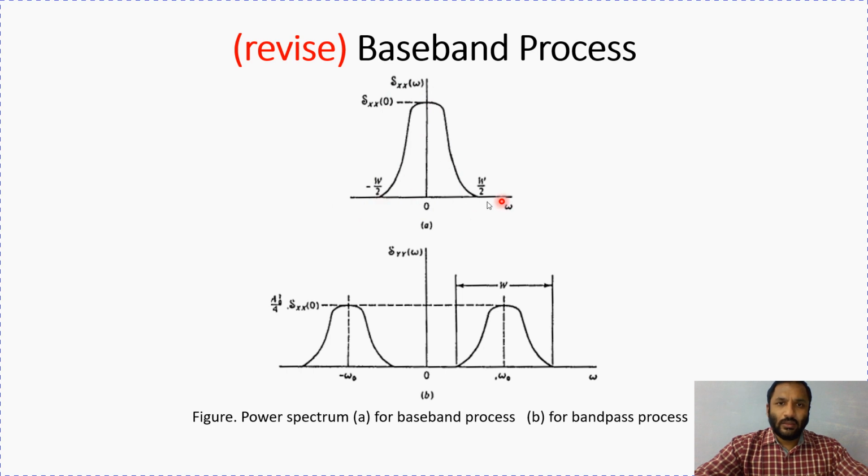And so for real world signals, the messages or the message signals as they are called, the power density is usually clustered around 0. It means they only contain lower frequencies, low pass, or sometimes it is called baseband signals, because this is the band of frequencies containing 0, a baseband process.